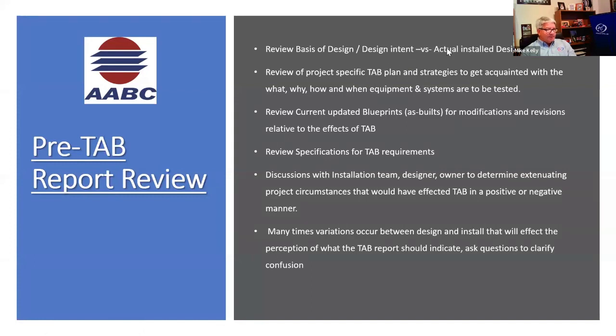Is everything accessible? Is everything installed correctly? Balanceability is a term that's been used over the years to say, can we actually balance this system? Or are all the flow meters installed tight to the slab, and we can't get our test fittings on the test ports for the flow meter, because all the valves and the handles are pointed straight to the top deck and we can't get our instrumentation on it to test water flows.